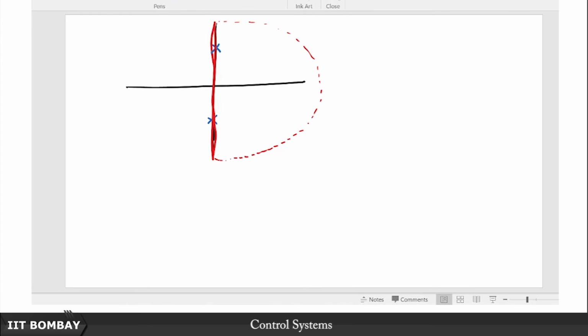When we take some examples and sketch the Nyquist plot, you will see that a large part of the Nyquist contour is about plotting or mapping this j omega axis, the imaginary axis of the Argand plane. That is why it is a frequency domain tool, just like the Bode plot, where we were concerned with the behavior on the j omega axis.